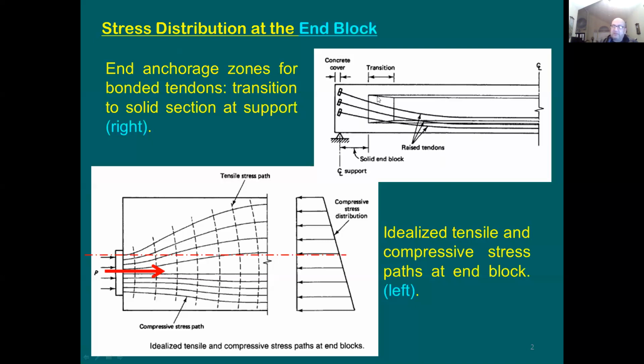As you know, if you imagine a concrete cylinder and you start to put vertical pressure on it, you start to increase the stresses by adding more force to it. All of a sudden, you're going to see that you're creating a vertical crack in it. This vertical crack happens because the concrete wants to expand laterally. So imagine that once you put the stresses from the end, you're going to have a longitudinal crack throughout the beam in the block.